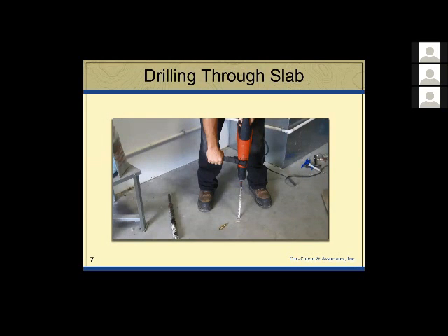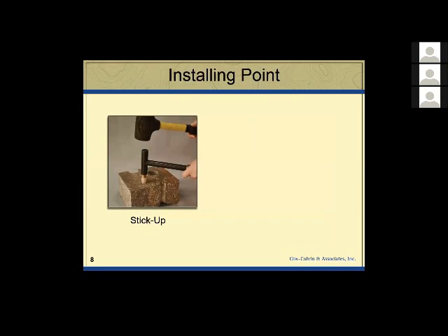Installation is simple. You drill a 5/8 inch hole, dust it out, hammer it in. We've put in as many as 90 of these things in a day, just 2 guys and a hammer drill. So they definitely go quick. On the left, I've got a stick-up configuration. This is if you don't mind having 3/4 of an inch of hardware sticking up above grade. So you put a traffic cone on it, come back and sample later in the day, pull it out and plug it when you're done.